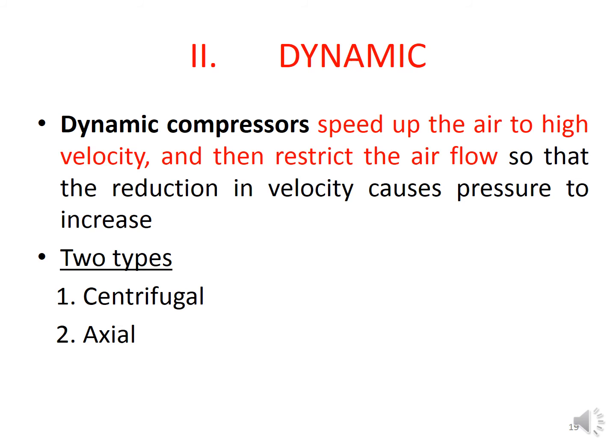Now let's go to dynamic compressors. Dynamic compressors speed up the air to high velocity and then restrict the airflow, so that the reduction in the velocity causes pressure to increase. These dynamic compressors are similar to our dynamic pumps. As I told you before, the classification, application and working principles are almost the same.